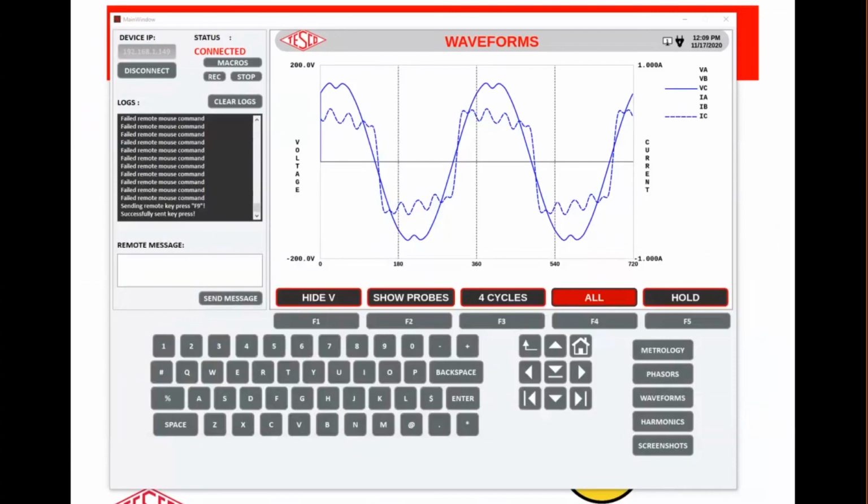Do the harmonics generate more heat than a regular pure sine wave at the same RMS? If we're talking about in a transformer, the answer is yes. And it's because a transformer is not uniformly efficient as a function of frequency. Power transformers are designed to be as efficient as they can be at 60 hertz.